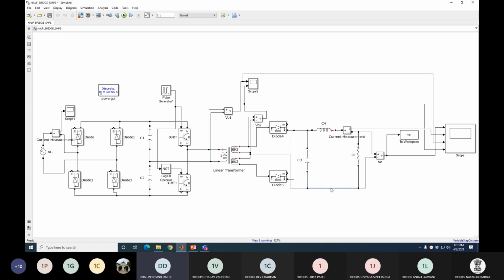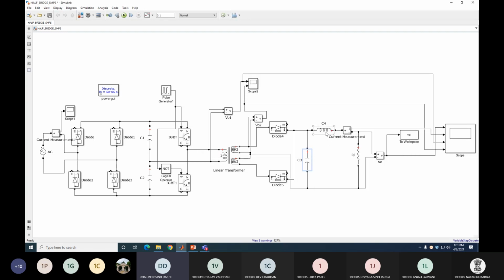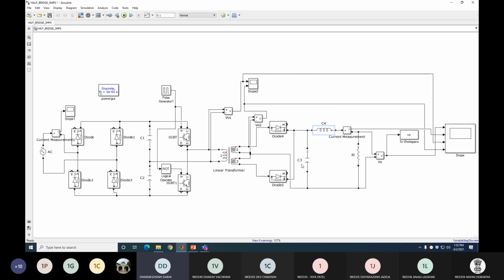And you must provide the center tapping here at the secondary side, and the terminal is connected to the load. Here I take a resistive load of 100 ohm and take the LC filter: capacitor 100 microfarad, 100 raised to minus 6, and inductor value 1e raised to minus 1, means 0.1. Actually you have to design this value of LC based on the power rating. Here I take this value of LC directly, in such a way that it gives me almost pure DC.